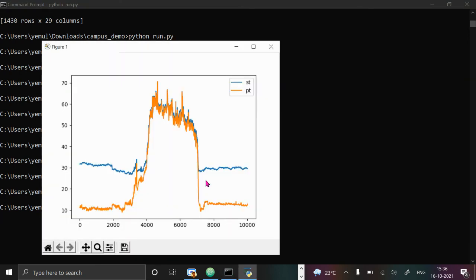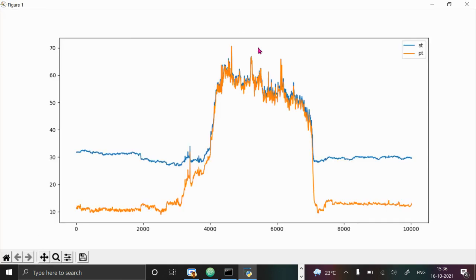Here you can see now, when the power factor is high, both are almost matching, so no problem. But instead of paying for consuming 10 kilowatts, you will be paying 3 times more money for consuming 30 kilowatts. This is because the billing is done based on the blue line, whereas the actual consumption is based on the orange line. So you are paying more bill. Immediately we can notice that in this case.